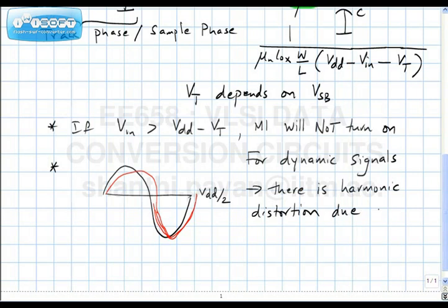You do, and this is coming because of the dependence of R on Vn. And please note that I am considering Vn well within that range before the switch gets. So clearly there is an issue with this thing. So the next idea is to say, hey, maybe NMOS was a bad idea. Perhaps we should try a PMOS transistor.